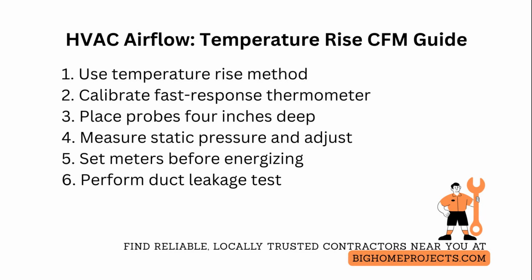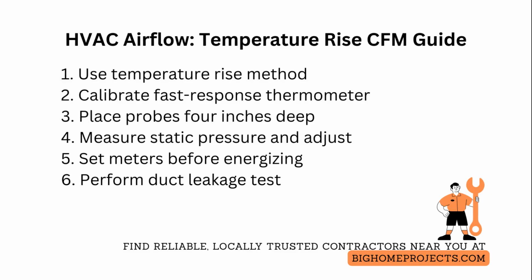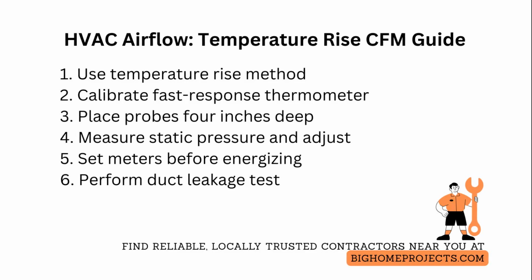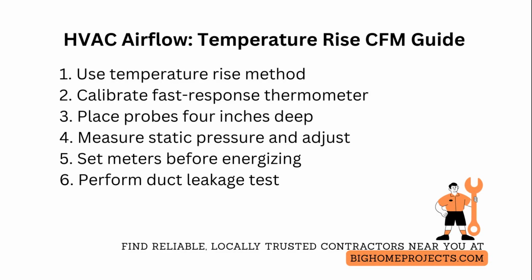When using clamp meters and multimeters, set ranges and connect all test leads before energizing, then step back and energize remotely where possible. Use current transducers rated for the expected amperage and verify true root mean square measurements for non-sinusoidal motor currents. Account for return leakage by performing a duct leakage test or comparing total register CFM to calculated system CFM, and add or subtract leakage in your airflow budget.